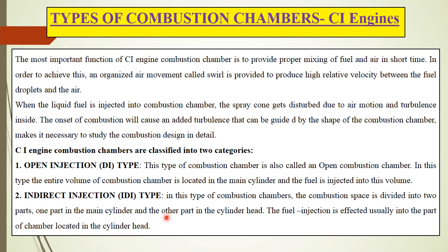That's why the construction is very precise, and that's why it is an expensive one. The fuel injection is usually effected into the part of the chamber located in the cylinder head. Indirect injection types are again classified into different types, namely swirl chamber, pre-combustion chamber and air cell.